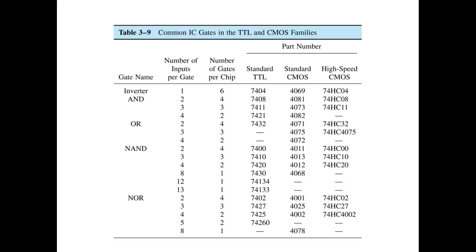But remember, that could be a 7404. It could be a 74LS04, right? You understand that. Or it could be a 74HC04. And if you were looking for the pin out, then they would be the same. A 4069 is a CMOS inverter, and it does not have the same pin out. So if it's got this same sequence of numbers, what this tells you is the pin out is the same, right? Y'all understand that?